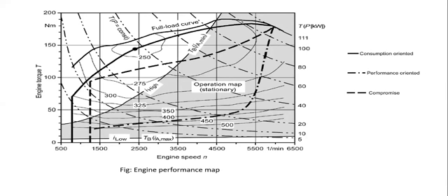A dynamometer is essential equipment for conducting these tests since it can be programmed to simulate the road conditions. The engine is loaded by means of a dynamometer, and the torque, power output, economy, and emissions are measured against speed and other factors that have a certain effect on the engine output. The performance curves are plotted manually or by computer and represented graphically. The behavior of the engine is studied when subjected to changes in the following parameters. The parameters could be the speed, the load, ignition timing, air fuel ratio, engine and ambient temperature.